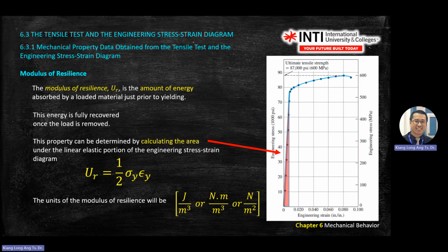From here, to find the yield stress, you need the 0.2% offset analysis, where the strain value of 0.2% will be here, 0.002. Then you draw a parallel line, you will get an intersect with one point here, move to the left, and you get the yield point.